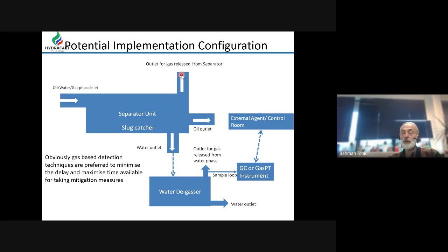So if we see the sign of hydrate formation at time 0, and then gas resulting from hydrate dissociation at time 1000. If the slip velocity is 10 meters per second, it shows that hydrate formation is happening 10 kilometers away. So we can detect where this hydrate is forming. Then we can decide whether depressurization is better or injection of inhibitor.